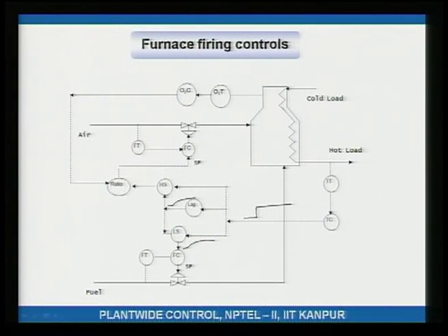So, the set point of the fuel is increasing as a lag. Okay. Let us look at what happens here. The signal here is a step, this signal is a lag. When you compare the two, the higher one of the two is this one. So, therefore, this passes through. So, therefore, this signal is this.